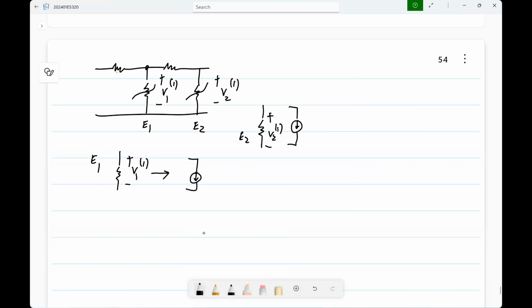Now, what is superposing? You will get the same thing, right? Because the analysis you are doing is of a linear circuit. Whether you do it with only this source or that source or both together, that is more a calculation thing. You could put all the current sources together and calculate, or do it one at a time, right? But the step 2 is completed only after you do it for all the sources and add up the results. You understand?